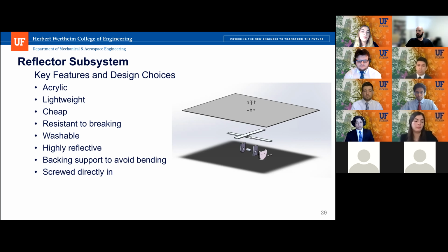Additionally, acrylic is also very cheap. A 1 meter squared sheet of 2 millimeter thick acrylic mirror can be purchased for $1.44, whereas a 2 millimeter thick glass mirror can be purchased for $3.10, which is twice the amount of the acrylic. Acrylic is also resistant to breaking. In terms of impact resistance, acrylic mirrors are 17 times stronger than glass, so it can survive greater impacts such as collisions and crashes without the concern that it will shatter.